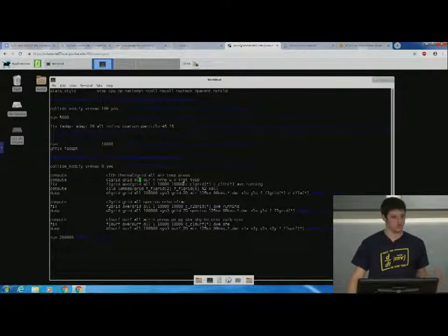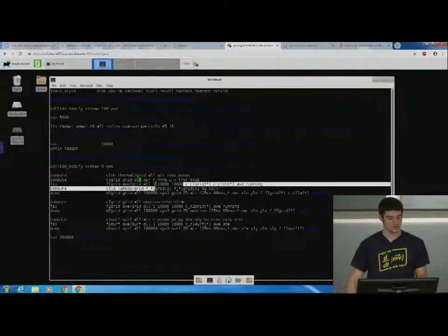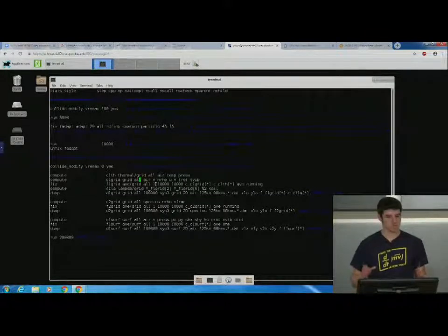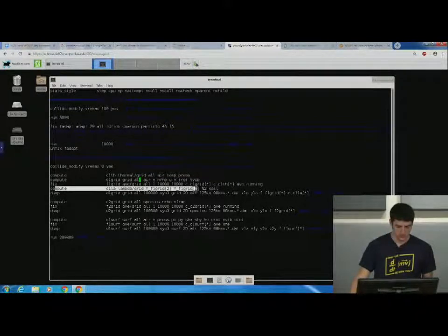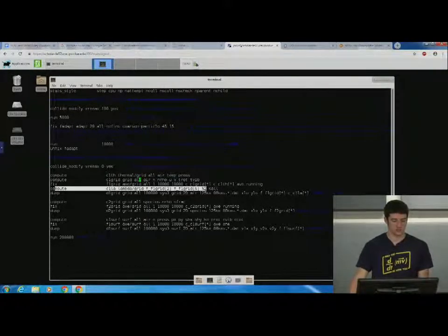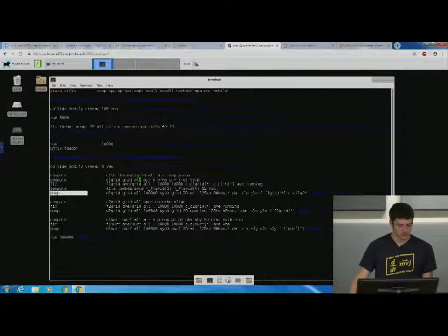Personally, I don't really get the point of reducing it, so I just do 1, 10,000, 10,000 like that. That way I'm repeating over enough steps. 10,000 steps is in most cases enough to get a pretty good sample and not have noise. And I'm repeating over every step. I'm going to ignore this command because you probably aren't interested in it, but if you're interested in a specific mean free path or Knudsen number or something locally, this will give you that. Generally, I haven't found it too useful.